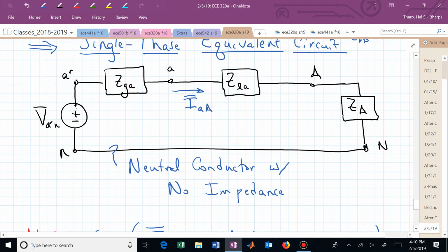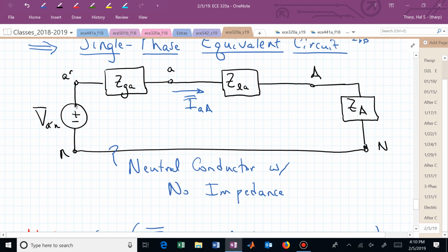So if you're wanting to solve these three-phase circuits, if you now have a YY configuration, you can immediately, if it's balanced, pull out the A phase or the B. Usually, let's just agree to do the A phase and solve it, and now we can get anything we want for the other phases based on the solutions here.